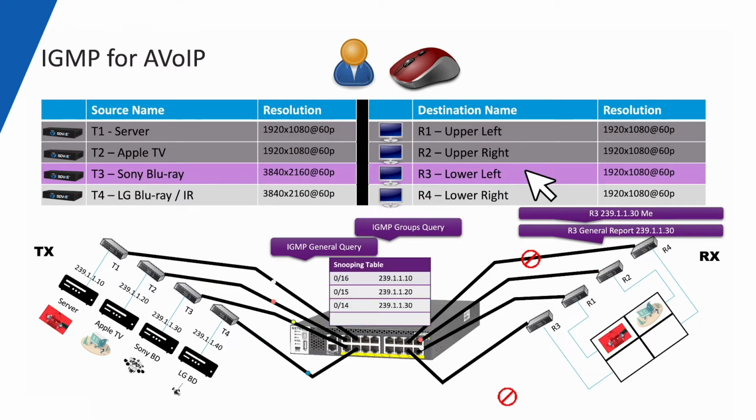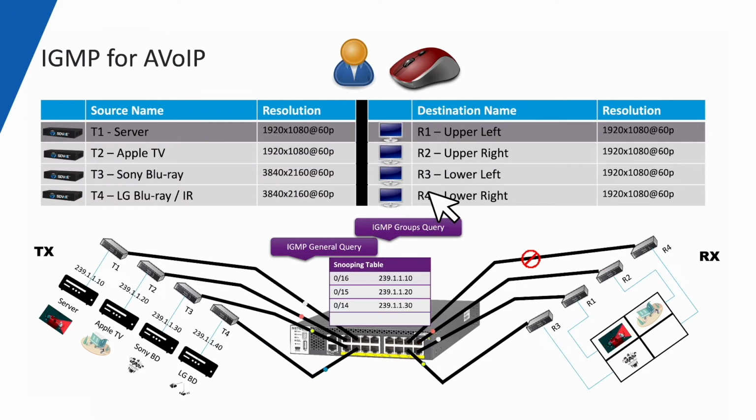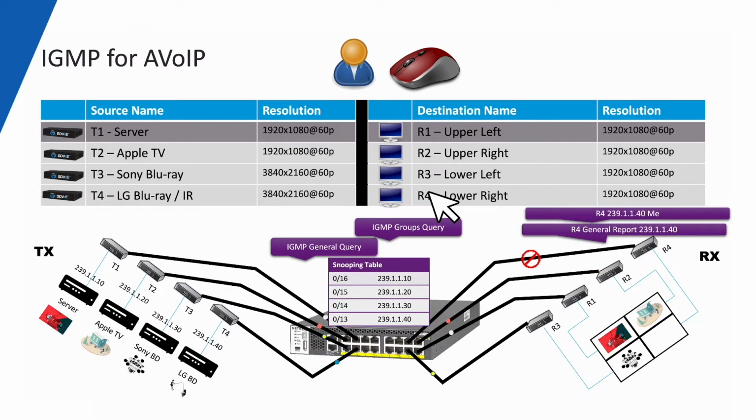All right? So again, it's really important to understand that the querier is absolutely mandatory. Without an IGMP querier, AV over IP couldn't work, because those video SDVoE endpoints couldn't let the switch know what to do. All right, so let's accelerate now.